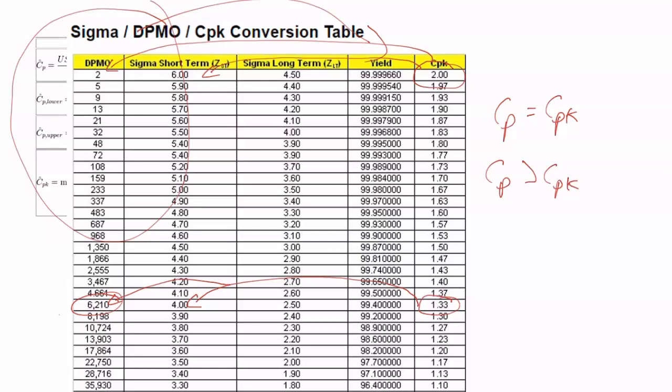Your typical CP, CPK values are between 1 and 2, which is the equivalent of 3 to 6 sigma level of performance. Because CP and CPK are frequently used as performance metrics for tightly controlled processes, it's typically not a metric that I'm using for human-facing or highly variable service-related processes, where these levels of performance are near impossible to reach. I'll use other techniques like our percent in, percent out type scores.